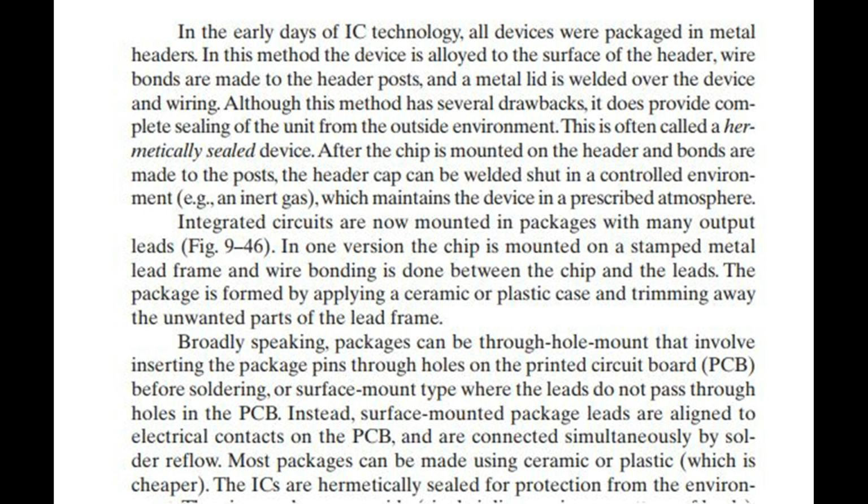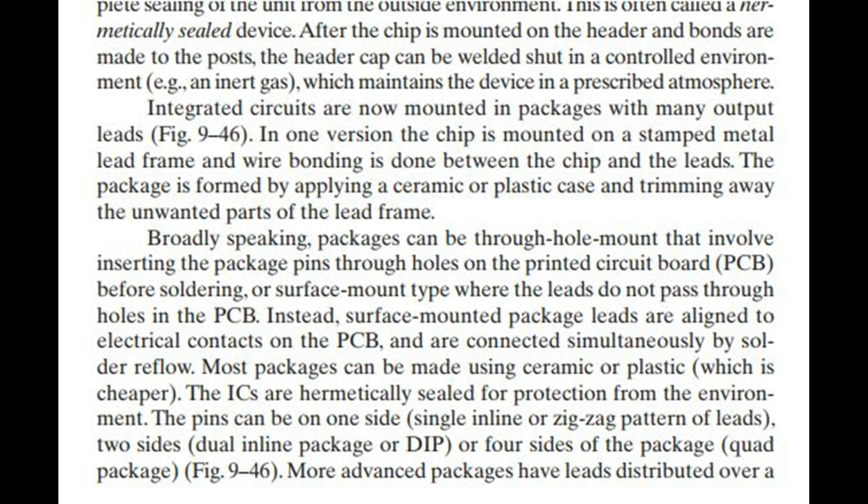Most packages can be made using ceramic or plastic, which is cheaper. The integrated circuits are hermetically sealed for protection from the environment. The pins can be on one side, single inline or zigzag pattern of leads, two sides, dual inline package or DIP, or four sides of the package, quad package, Fig 9.46.